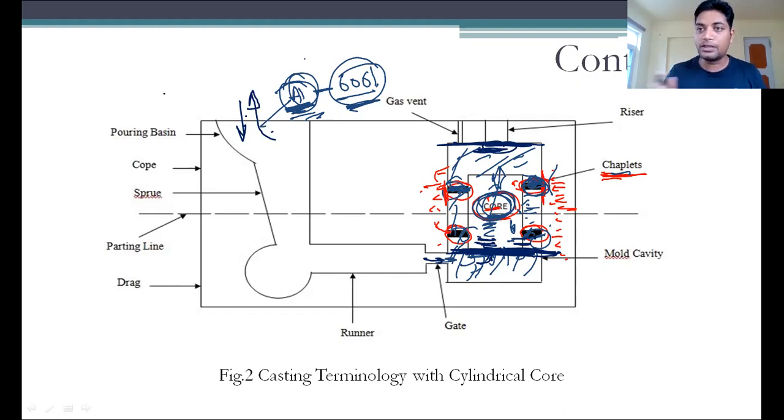So what we are doing is, if there is a necessity, yeah, your one question is valid here: we want that this liquid material should come out from the riser. So if this molten material which we are pouring becomes solid in between, only in between the surfaces, then we are creating two surfaces differently. Means if the height of this cylinder is high enough that the molten material we are filling completely solidifies in between only, then definitely whatever space is there at the top, we cannot fill that material, okay.